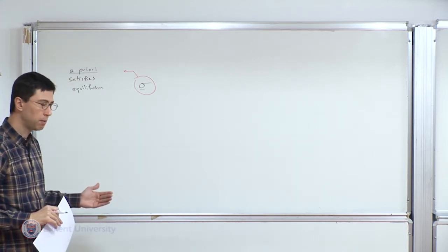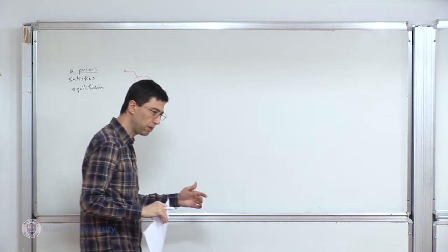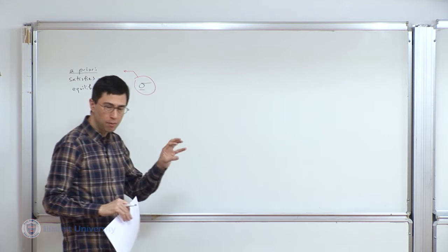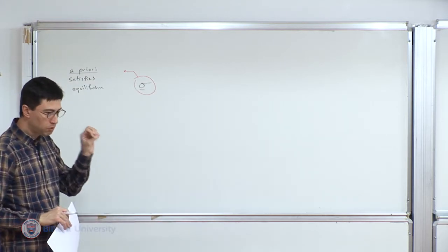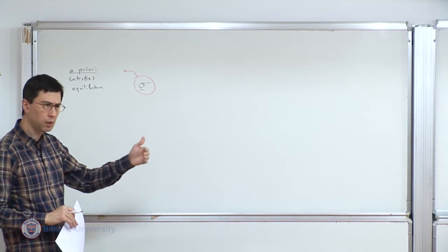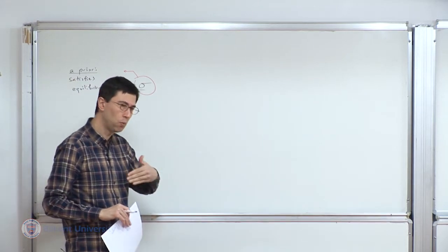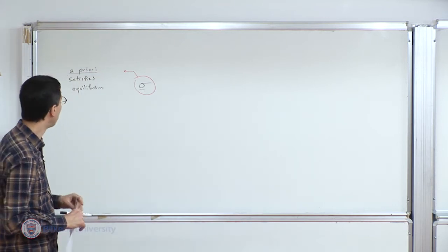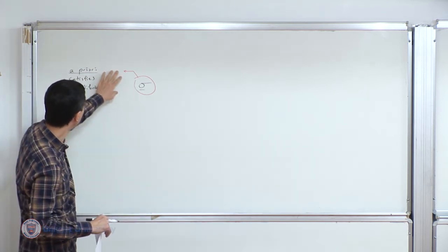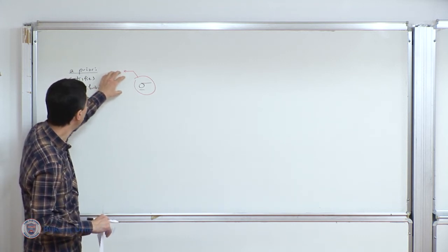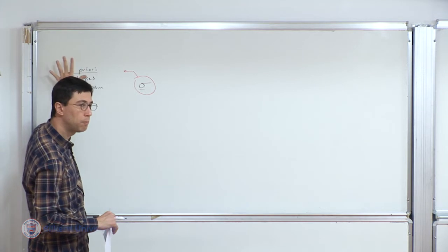Unlike the displacement-based approach, where equilibrium is what closes the loop and allows us to restrict the form of the solution. We start with a relatively general but simplified form of the solution, and once we enforce equilibrium, we get the particular form. In this case, from the outset, we assume that the stress, our primary solution field now, satisfies equilibrium.